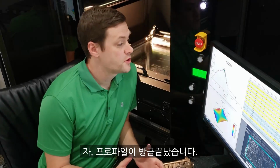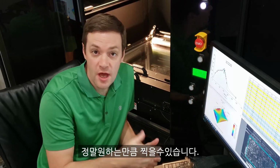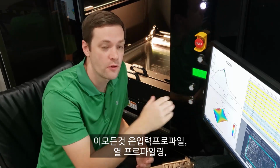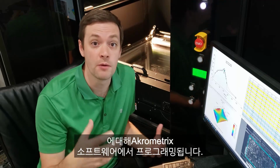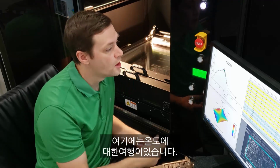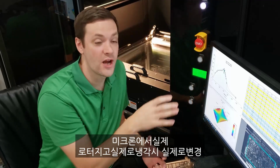All right, so our profile just ended. We got through a reflow process, took about 13 images through that. You can really take as many as you want. All of this is programmed in Acrometric software. The input profile, the thermal profiling, and then the analysis package is really where a lot of the complexity and the meat and the value comes with warpage. So here you have the excursion over temperature. You can see the board actually kind of popped and really changed on the cool down.